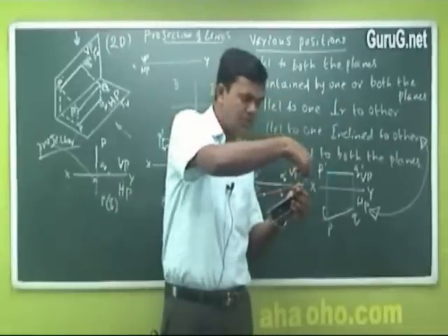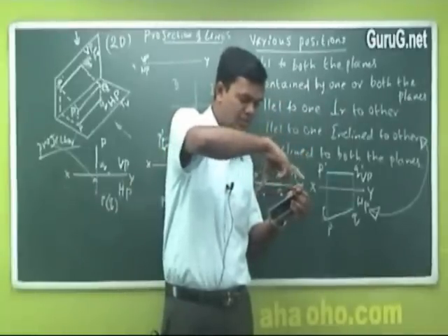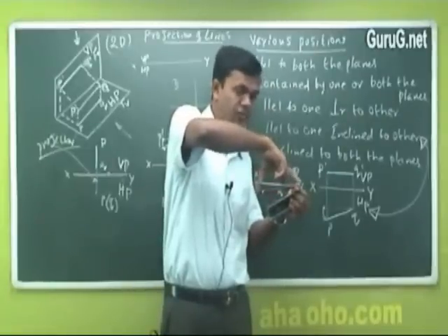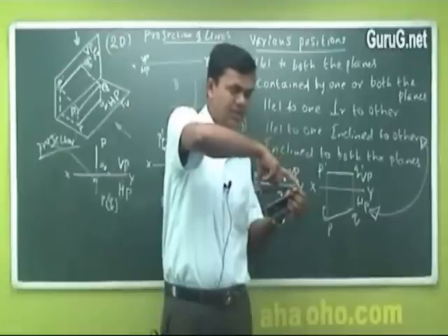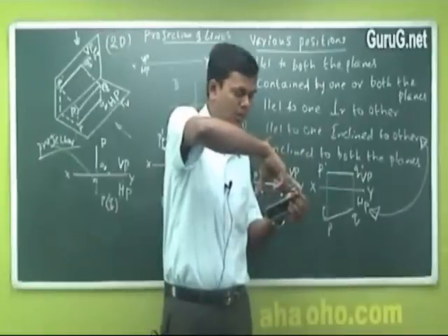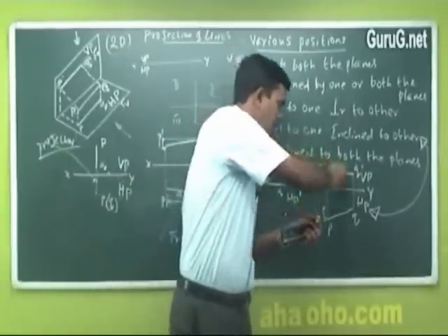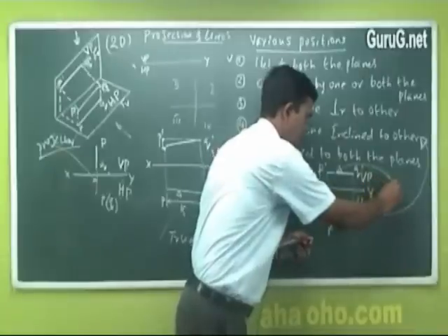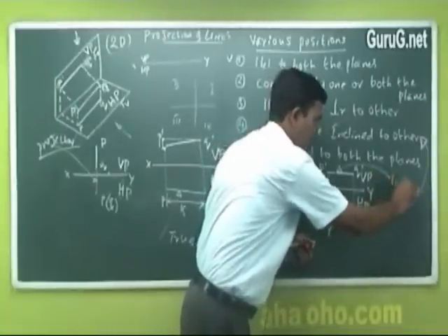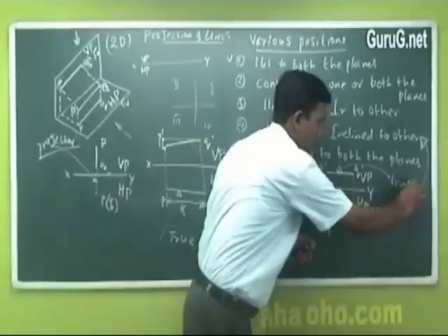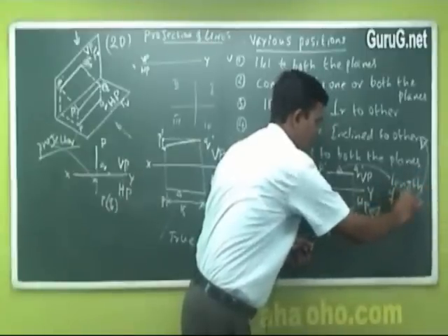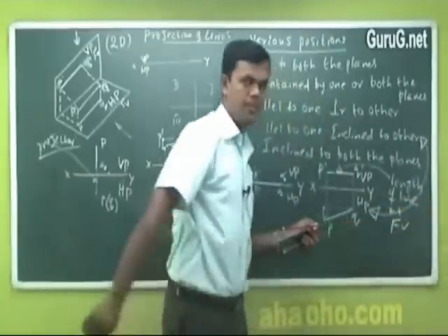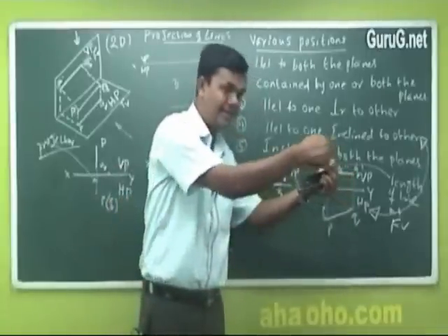But in the front view you see only the points P and Q. It looks like this, in this position. But actually it is this. I rotated, so this is the foreshortened length. But the 15 centimeters remains as it is, and this is the shortened length. So I will say the straight line, whatever you see, this is the length of the line at front view. Because in the front view, look, it's straight.